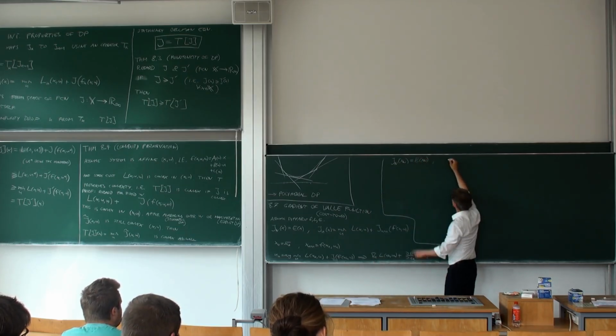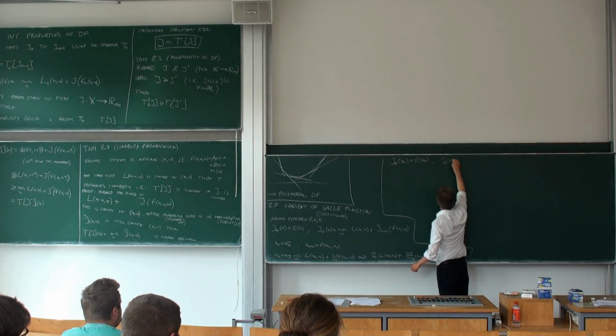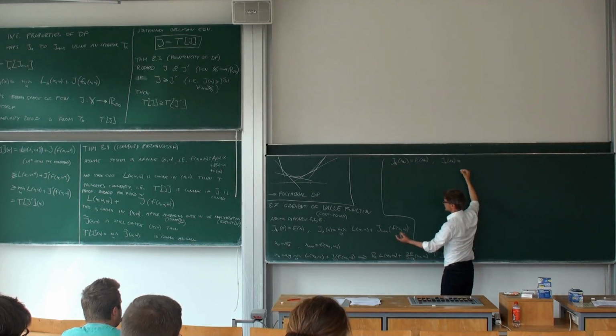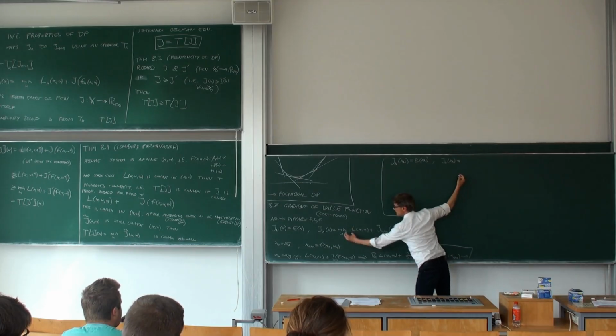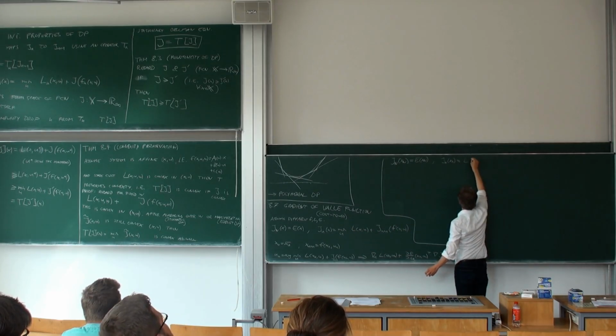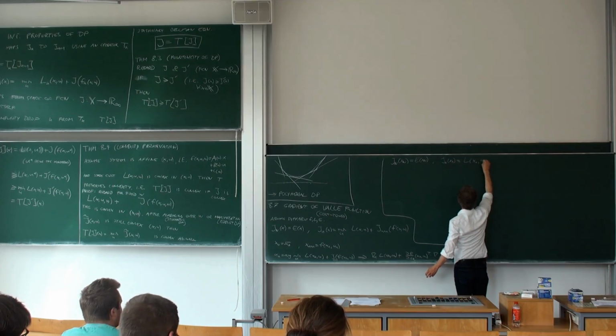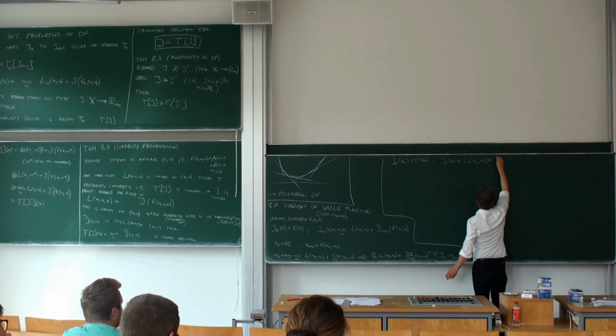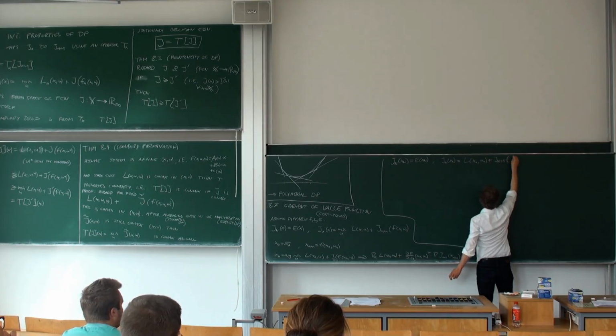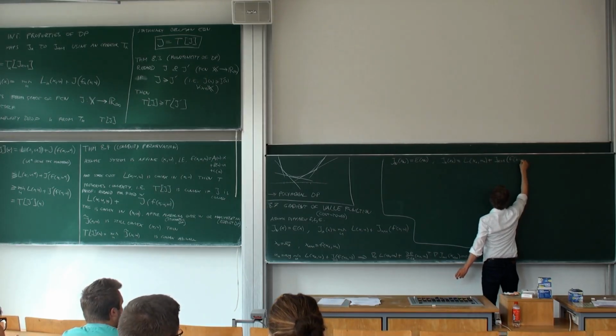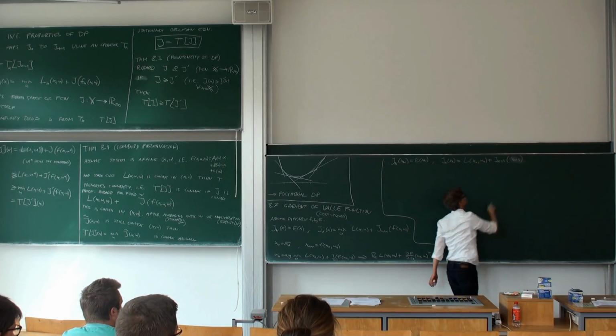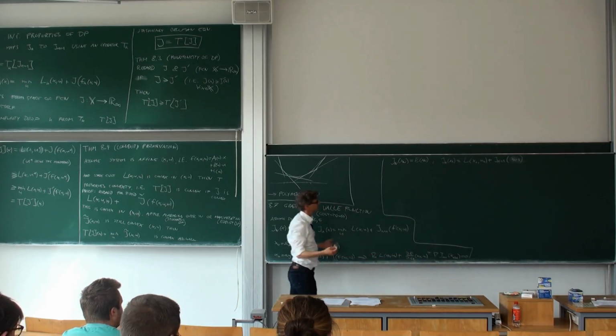Then also for J_k at x_k, I know that at the optimal trajectory, the minimizer of that whole thing will be u_k, so I will have this relation: L of x_k, u_k plus J_{k+1} of x_{k+1}. Here I can directly put x_{k+1} so I make it a bit shorter.